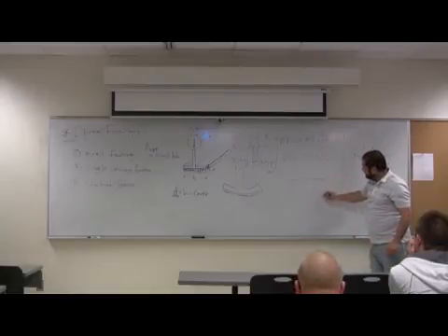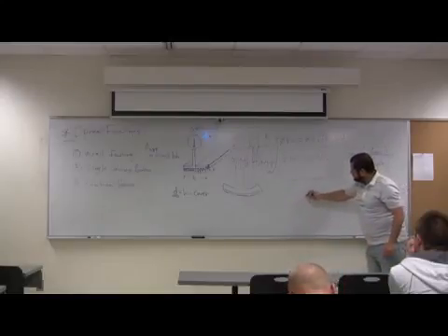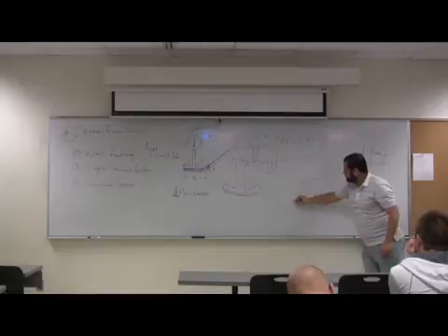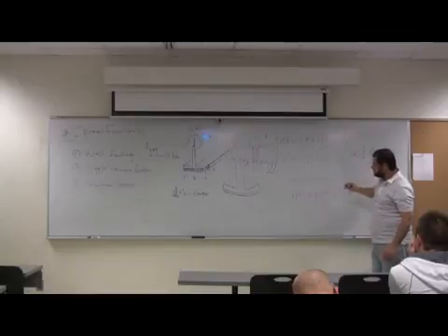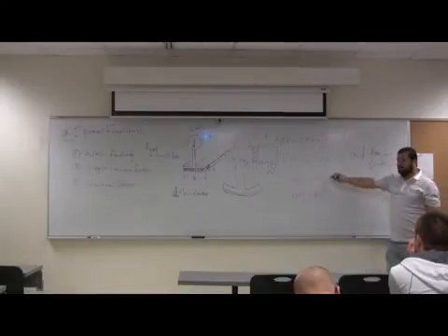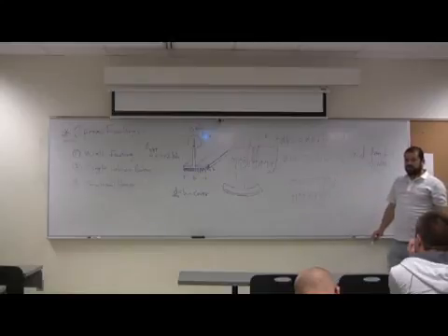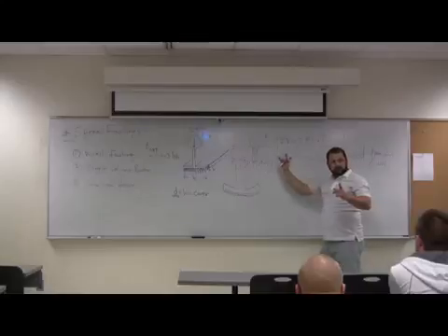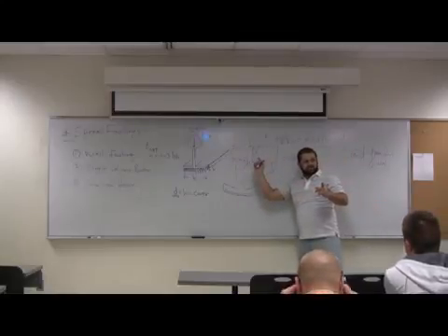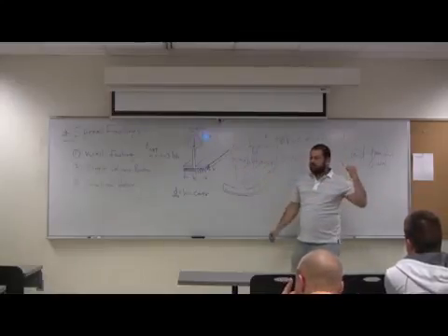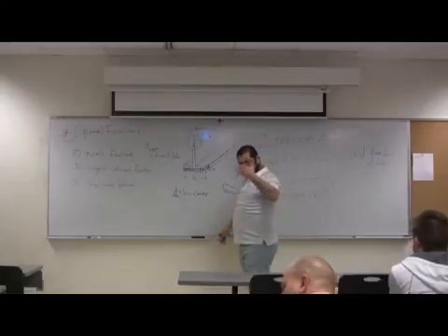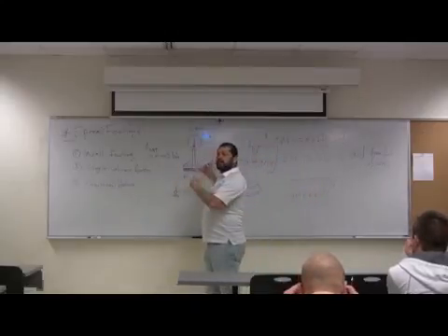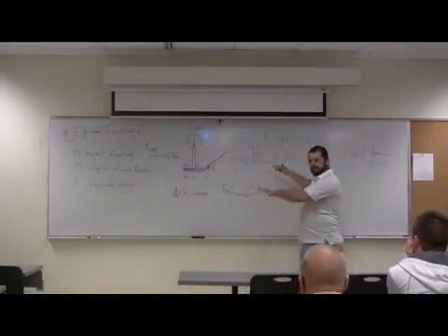This is the soil pressure. This is your d, and this is your Vu at d. Remember, we are doing a 1 foot strip, because the pressure will be specified per square foot, so it will be multiplied by 1, in the wall footing. Is it obvious?